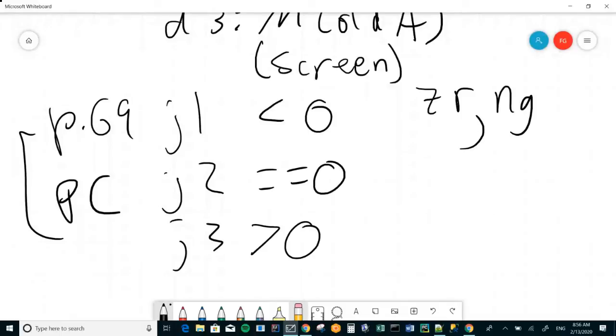So for each of these conditions in your circuit, you need to wire up when am I actually jumping. So for instance, if I want to jump on a less than 0, I both have to have this bit out of 1, and then I have to have my negative flag set. In other words, use an AND gate or whatever.